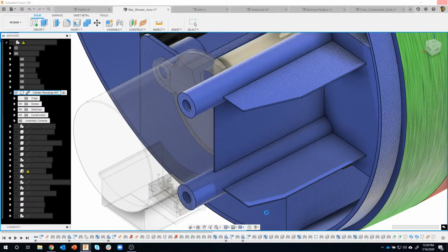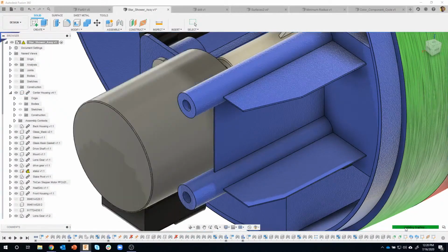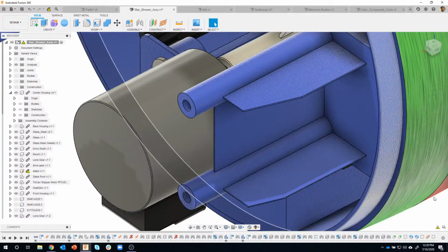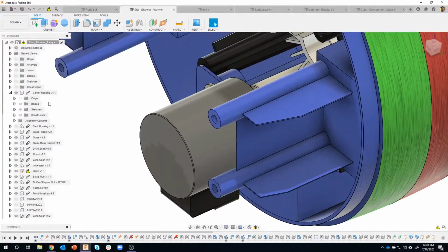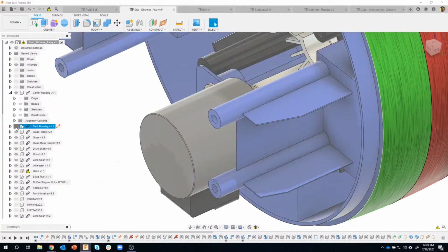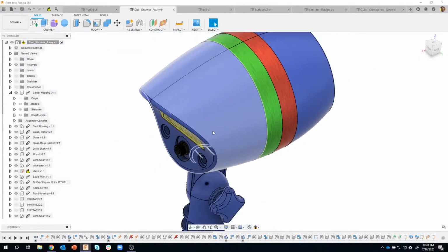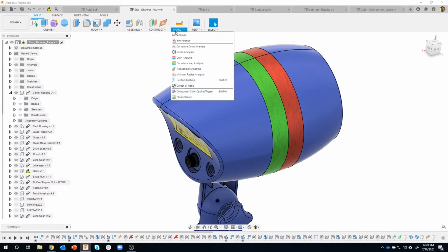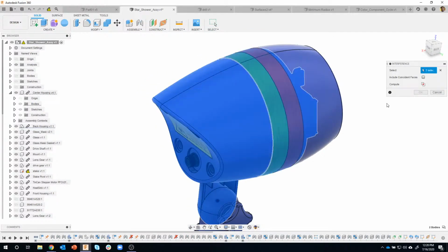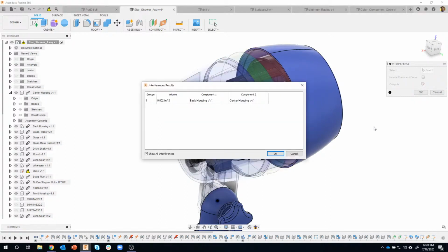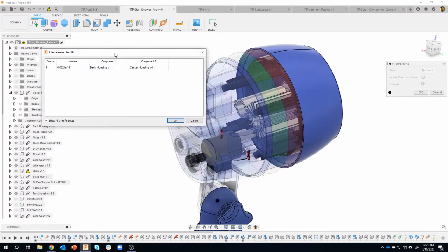So it's now updating my timeline, confirming that all of the downstream processes will work. So you can see how it's computing that. A couple of the axes didn't compute, but that's okay. And then let's turn the back housing back on. And I'll inspect one more time. Instead of doing the whole thing, I'm just going to pick the 2 parts that I'm concerned about. So you'll notice instead of 31 selected, it only says 2 selected, and I'll clash.